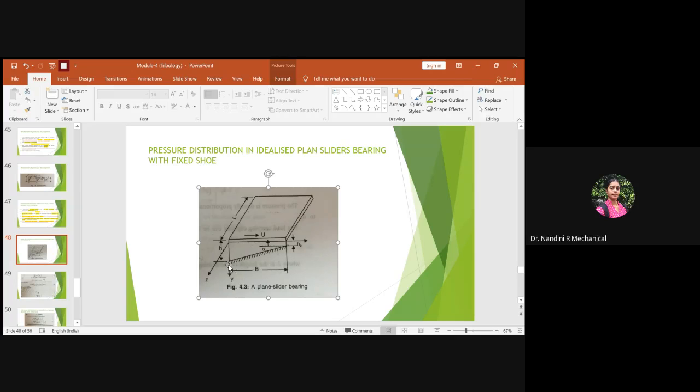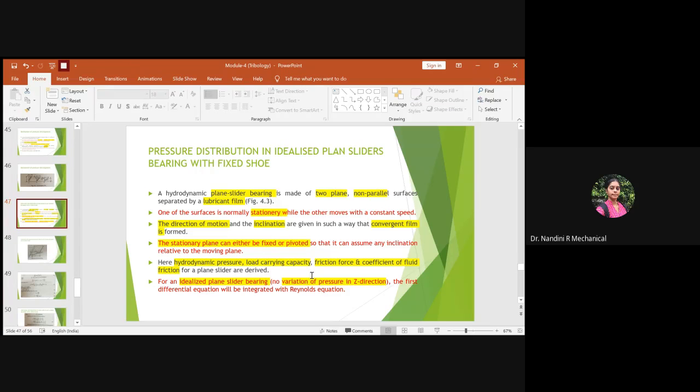So the layer of the fluid, the film of the oil which is touching at the bottom, will have a comparatively negligible relative motion. So to get the relative motion, it is necessary to keep one of the surfaces held stationary. That is the reason we are fixing the bottom layer as pivoted. So these things you have to understand clearly, right? Then you will get a relative motion as required with respect to the moving plane, right?